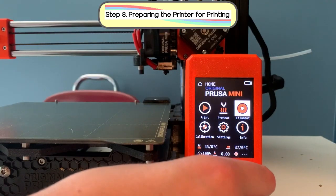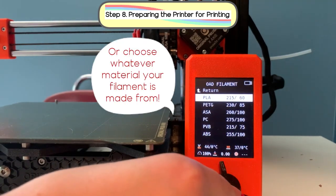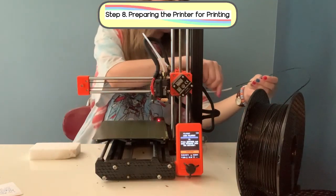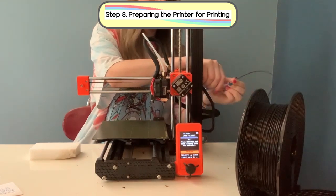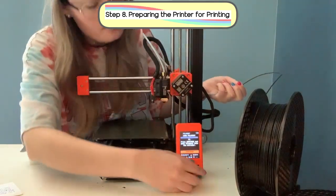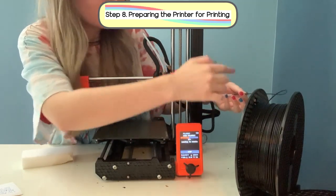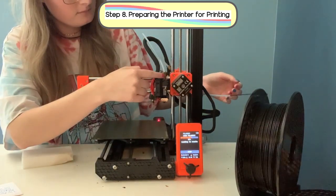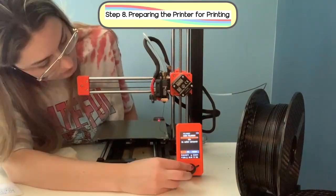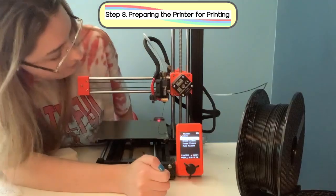To load filament, scroll over to filament, enter, hit load filament, and then select PLA. To load the filament, take the end, push it into the clear tube all the way until you can't push anymore. Make sure the wheel spins just fine. And then press continue. You should feel the filament start to move in and then finally go through into the extruder. And then it should come out the nozzle. Is this color correct? Make sure that it is and then press yes. If not, then hit retry.